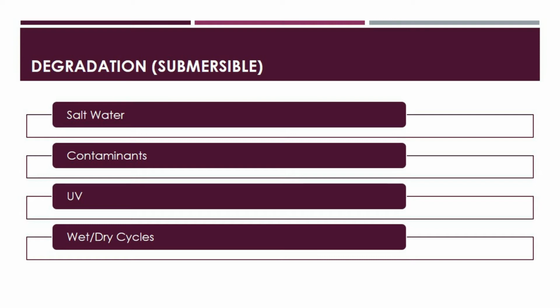Moisture will cause potential acids to develop when SF6 is exposed to it. Corrosive acids can cause insulation failure and corrosion of the switchgear units inside. When moisture or air enters a vacuum switchgear system, the quality of the insulating material deteriorates, which has a negative impact on the unit's internal workings.